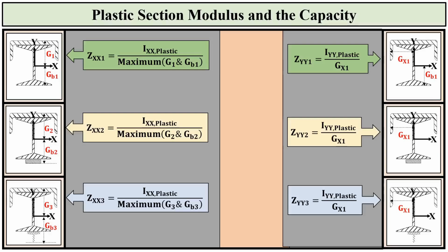This ensures we are checking the most critical point for bending stress along the x-axis, as well as the stress along the y-axis. Since the arrangement of the combined section is symmetrical about the y-axis, and the inverted channel at the top has the maximum web length, the perpendicular length of the extreme fiber from the y-axis will be exactly half of the channel's web length.